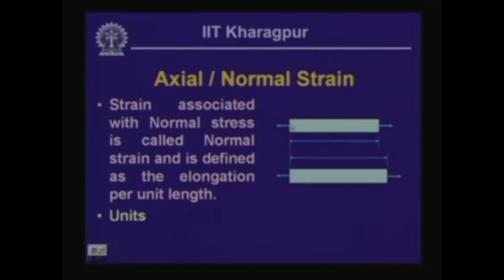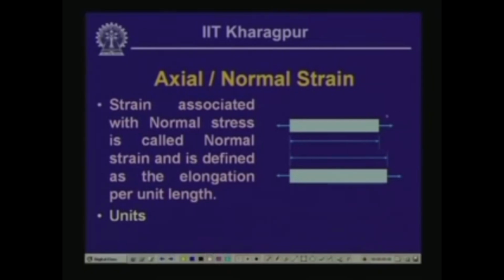Now, let us assume that we have a body which is acted on by force P. The length of the body let us assume as L. Now, when a body is subjected to either change in the temperature or subjected to the forces, it undergoes deformation, and in strength of materials we are interested to look into this deformation, and we try to define a quantity in terms of this deformation.